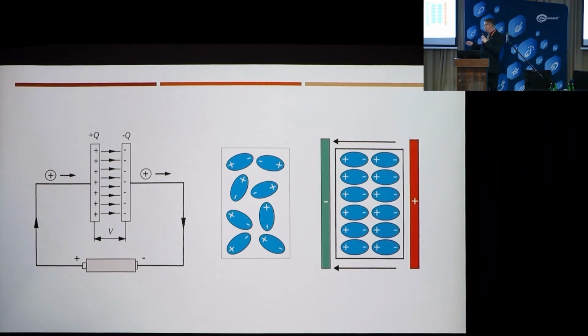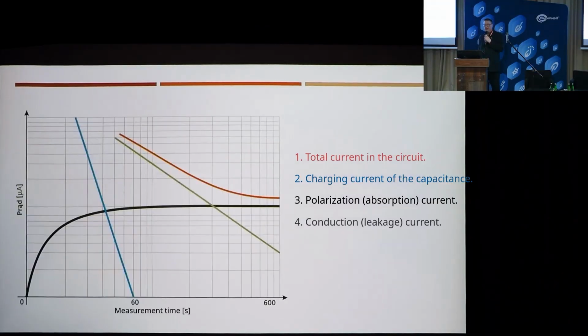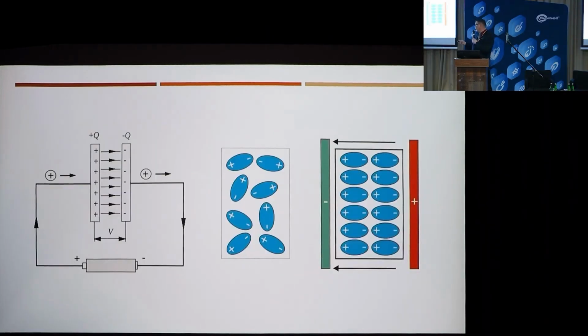So capacitance charging will occur in such an object. That's why at first the meter's entire output will be directed toward that, and a current will arise that will in fact charge that capacitance. But under the influence of the applied voltage, a field will form around that conductor, around the insulation. The structure of that insulation, or maybe I'd describe it as the molecules the insulation is made of, they behave a bit like a compass needle, and they'll want to align themselves with the direction of that field.